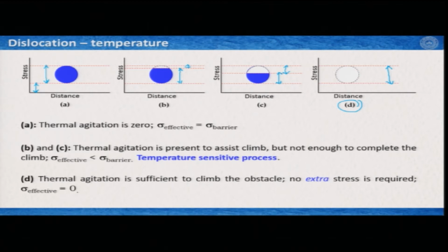So, at higher temperature, you do not need much stress to deform the crystals. And if you remember, in our rheology lecture we learnt that at higher temperature the strength of the material decreases drastically, and now you know the micromechanics why. If you have temperature, then the crystals get enough energy to move the dislocations and deform the crystal through the process of intracrystalline plasticity.